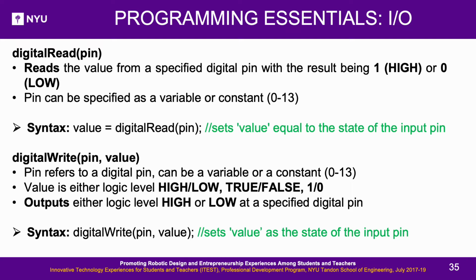digitalWrite(pin, value). Pin refers to a digital pin, and can be a variable or a constant from 0 to 13. Value is either logic level high or low, true or false, 1 or 0. It outputs either logic level high or low at a specified digital pin.